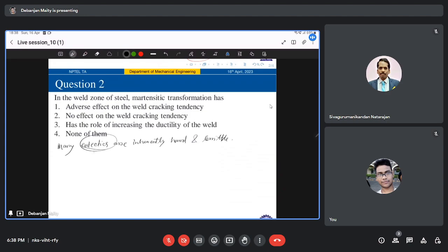So what are those eutectics? They are an intimate mechanical mixture of two phases, right? One of which is often much stronger, harder and more brittle than the other. The result, of course, is that the weaker, softer, but tougher phase is strengthened and hardened. However, the resulting two-phase mixture or constituent is also made less tough and less ductile.